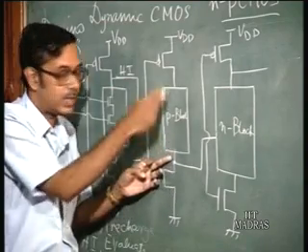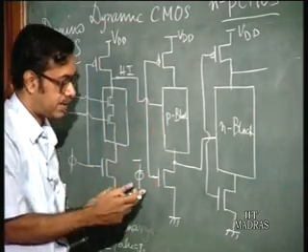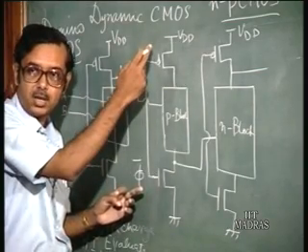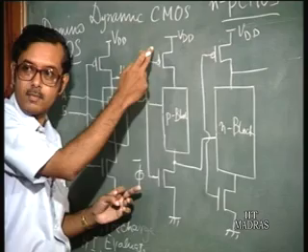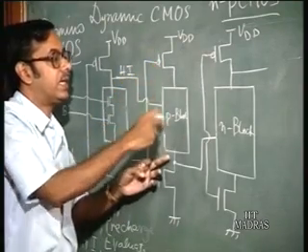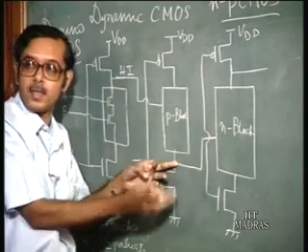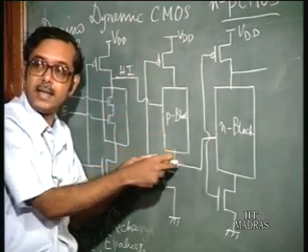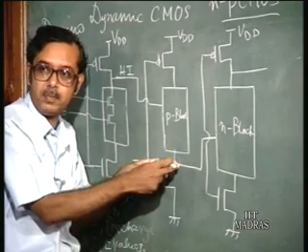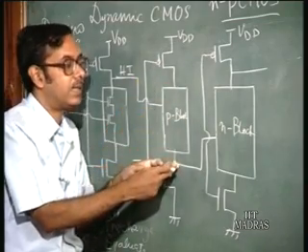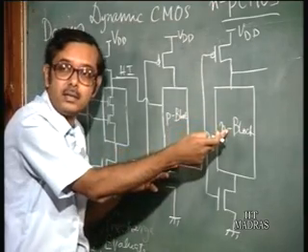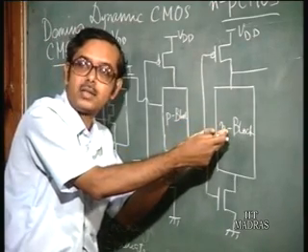All right. So, if this is conducting, in this phase this NMOS is off and the PMOS is on, because this is phi bar. So, if this is conducting, the output here, this is off. So, this can charge to VDD. So, this output of this P block here can go up to VDD, which means that this can turn on the next N block transistors.